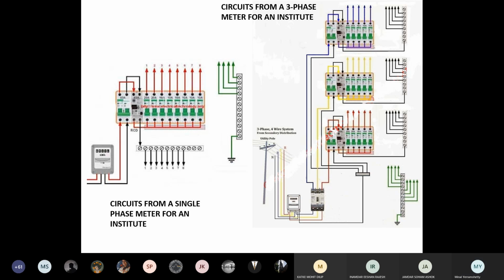The line comes in, I will not have the cutout. First I will do the distribution. I will distribute the line. Now the distributed line will go into 41 outlets. Once the line comes in, it goes to the bus bar, and then to the separate 41 meters. 30 are residential, 10 are commercial, and 1 is the society bill. Now it goes to the 41 meters.